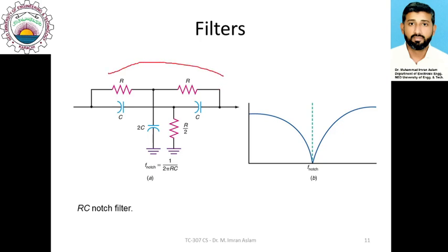This circuit diagram illustrates the implementation of the notch filter. You can see that we have a kind of double configuration of R and C. The shape of this circuit looks like a T, so that's why it's sometimes named the parallel T system. The response of this RC notch filter would look somewhat like this, which is illustrated in the diagram here.